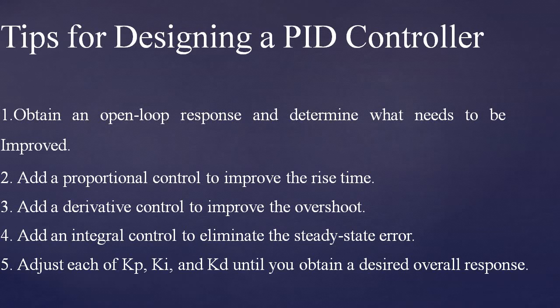Then add integral control to eliminate the steady state error. And finally, adjust each of Kp, Ki and Kd until you obtain the desired overall response. So these are some tips for designing a PID controller.